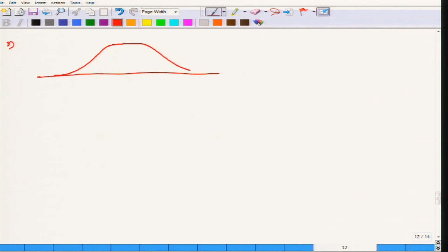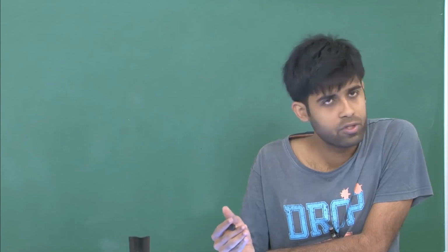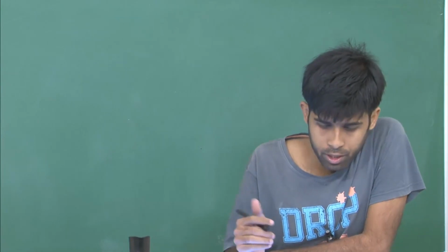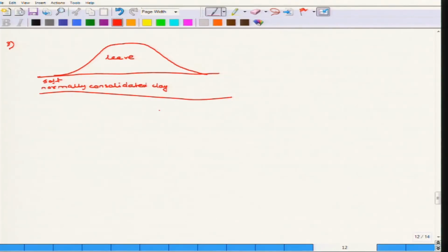So, in a third problem, illustrating the effects, it is described here. This is a levee, and here is a normally consolidated clay layer. Since it is a normally consolidated clay, obviously the effect of pre-consolidation we will not consider; we will only consider the virgin consolidation curve. That means we can approach it both by the coefficient of volume compressibility method as well as by the compression index method in order to calculate the settlement. Now, you see here that the soil profile again is not uniform.